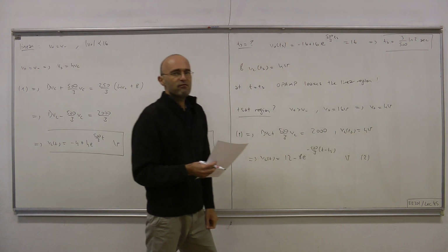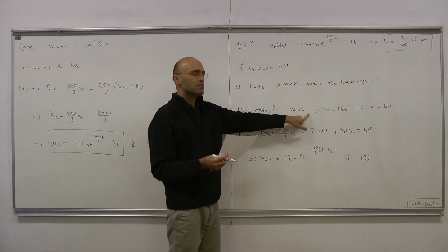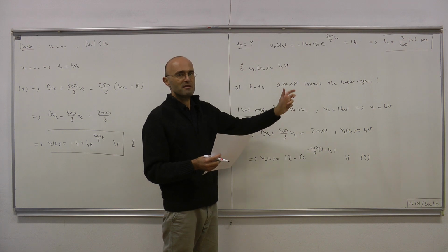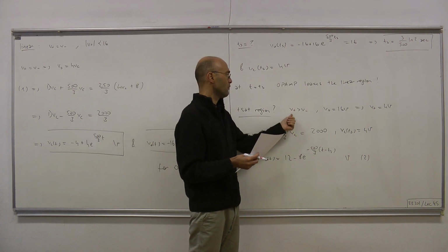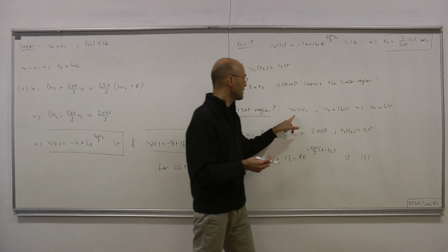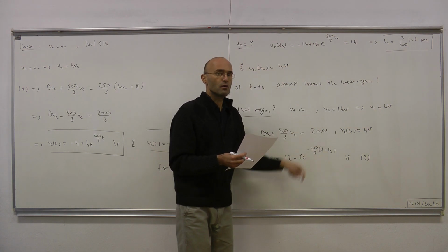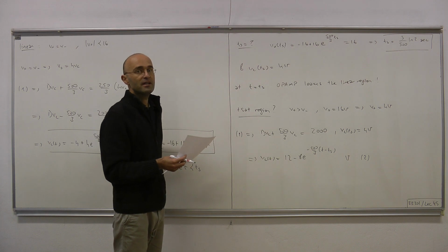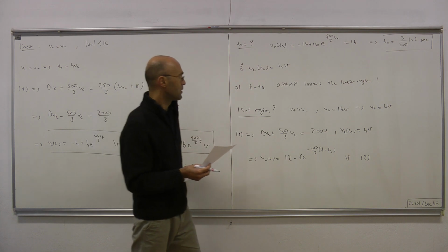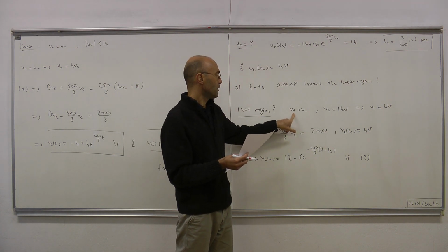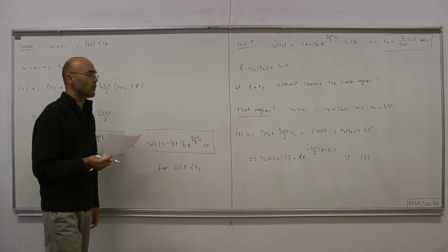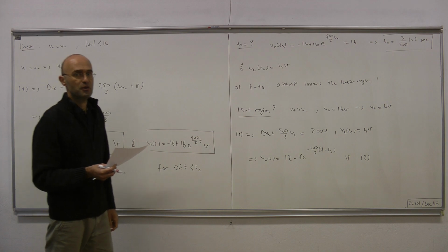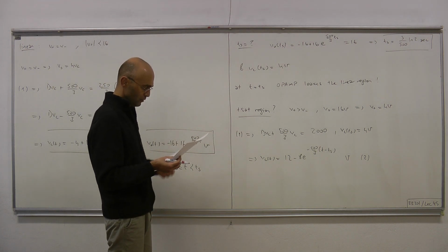VC becomes larger than 4 means that V minus becomes larger than 4, and then all of a sudden V plus cannot be larger than V minus. Because V minus is larger than 4 and V plus is 4 if op-amp is in positive saturation region. So that means the op-amp cannot remain in positive saturation region for any interval of time.